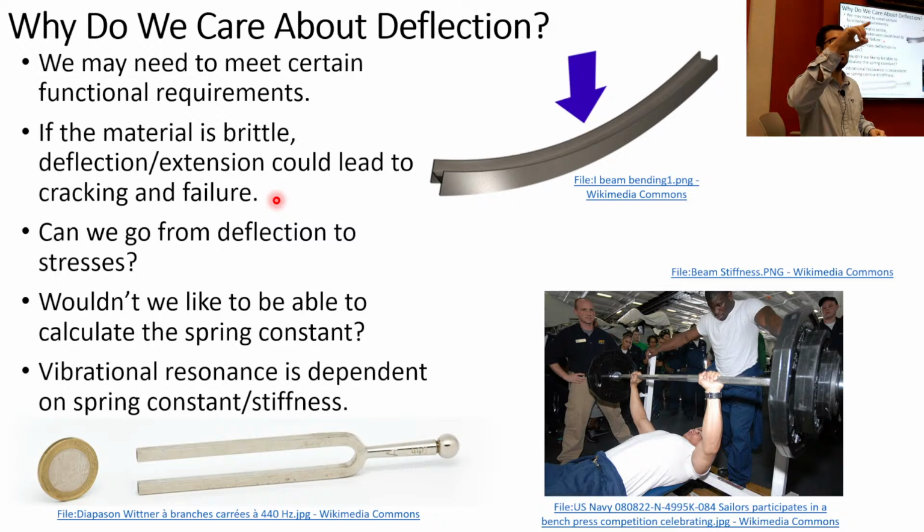If you looked at these frequency responses for the mass spring damper systems, there was this shoot up and then come back down. And it goes down as a factor of 100 per decade. A first order system goes down a factor of 10 per decade. A second order system goes down by a factor of 100 per decade.